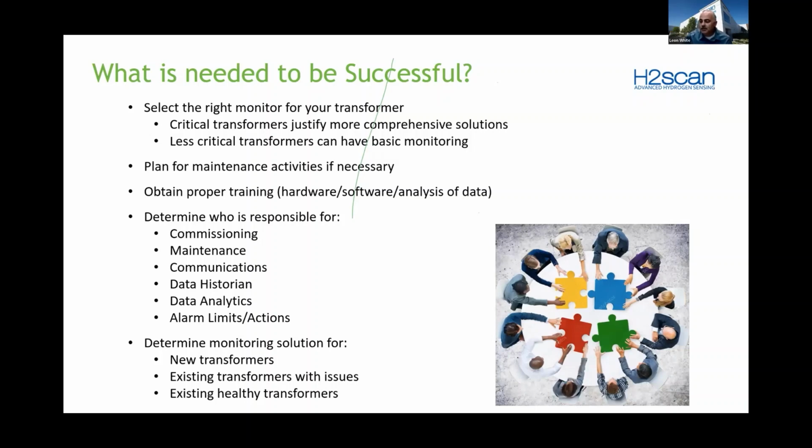And of course, once you identify which are your critical transformers and which are not so critical, and then the different levels of monitoring, you want to determine your solutions for your new transformers and your existing transformers with issues. A transformer with issues, you're probably going to want to put more monitoring on than a transformer with no issues.